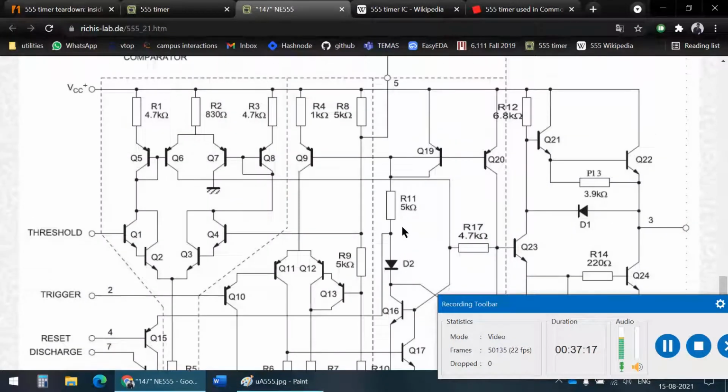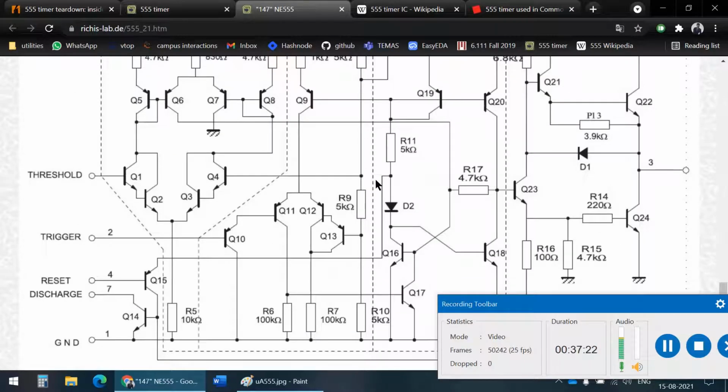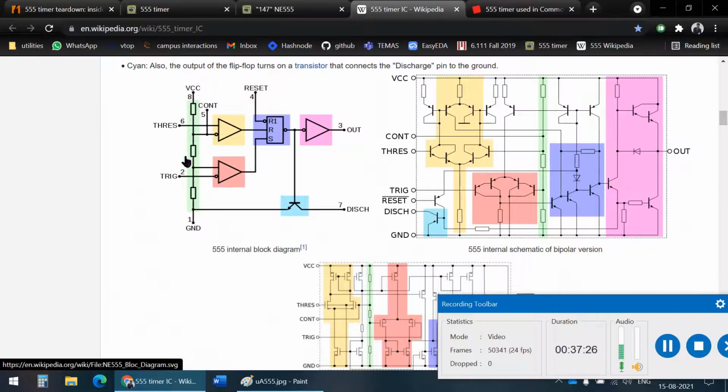So now the thing about the 555 timer is these are just 3 equal valued resistors. Look at here. This is easier. So these are 3 equal value resistors. The value at this point is 2/3 VCC, and the point here would be one third of VCC. And these are just 2 comparators.